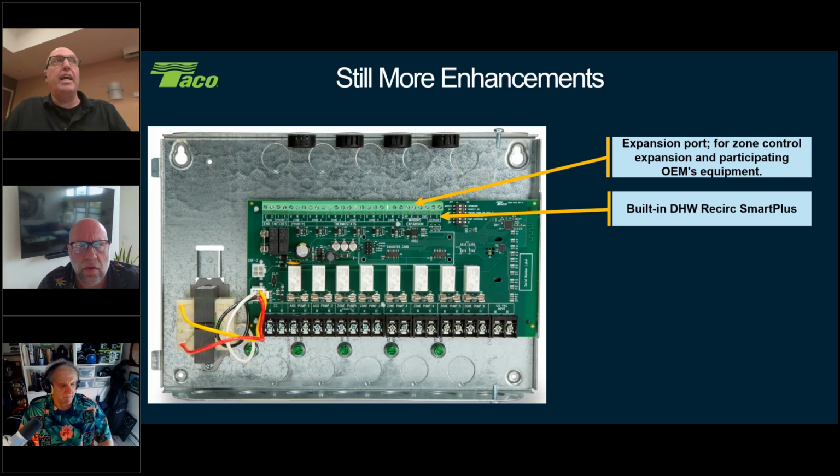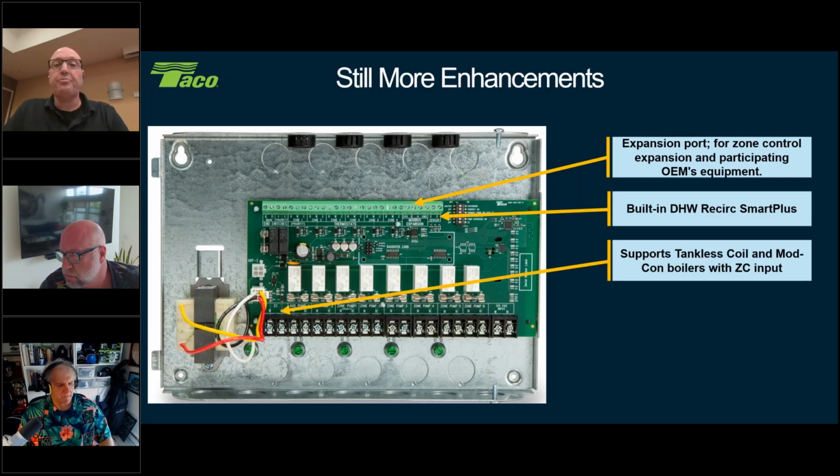If you have this relay on there, there's no reason to go find an outlet to plug that pump in. Auxiliary pump 1 is your recirc pump. You would just wire in your pump here, and we have the same functionality as the smart plug does. That's built into the board itself. If you're not using it, then you don't need to wire anything to it. It's just a standard 10K sensor. It doesn't come with the board, so you'll have to get your hands on that.